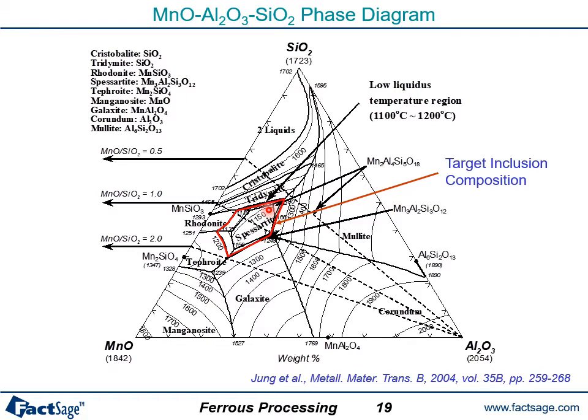So this is the main reason why people were interested in MnSi deoxidation. Instead of the solid alumina inclusion, you can make a liquid inclusion, which is more suitable for those special alloy applications. Then why are we not just looking at the MnSi binary phase diagram? Because during the steel making process, aluminum can come as an impurity from many different sources.